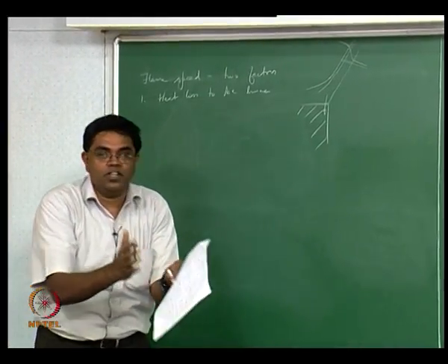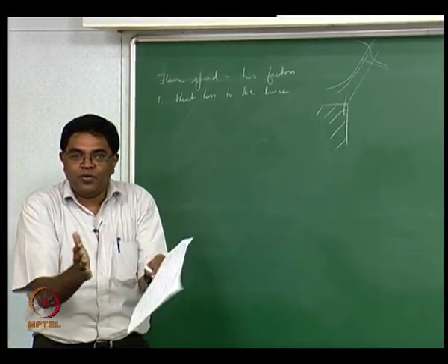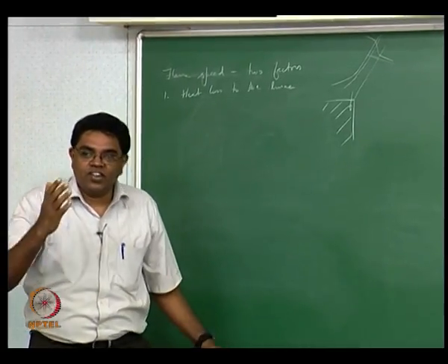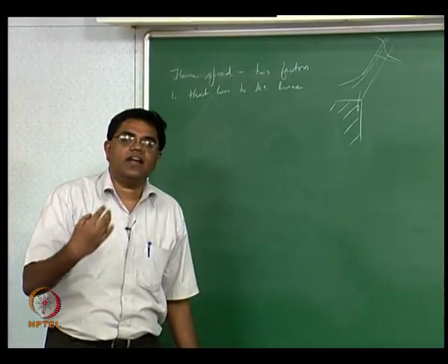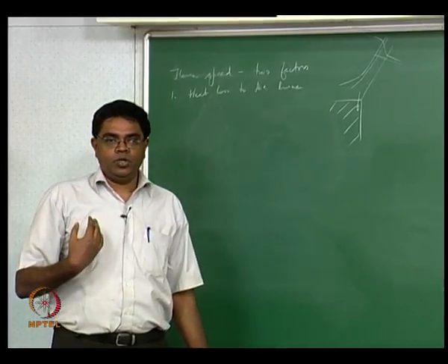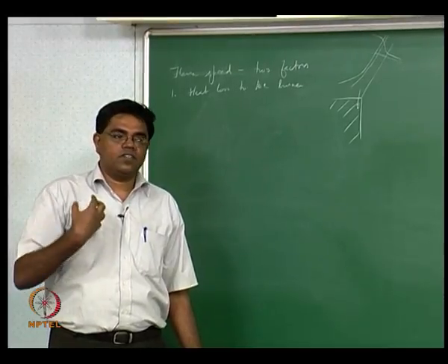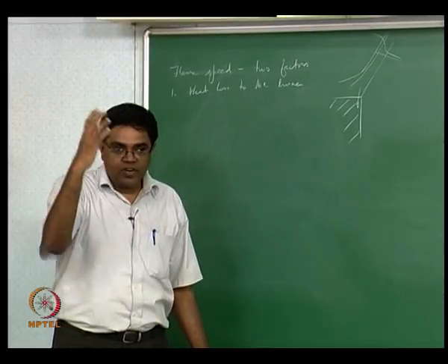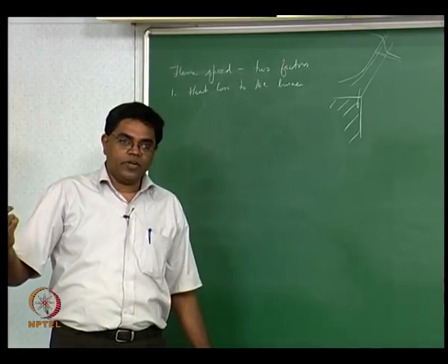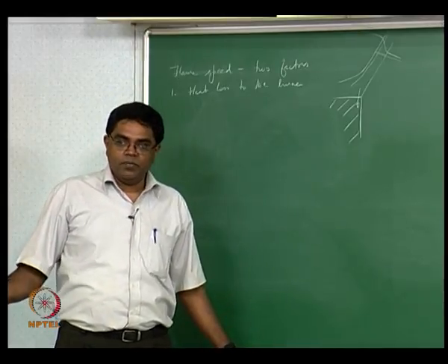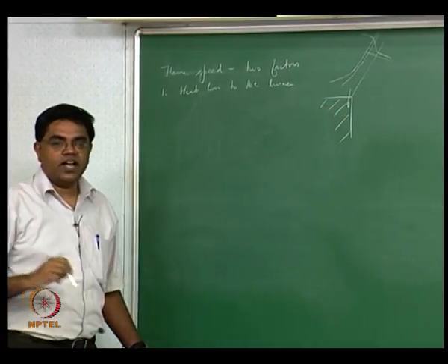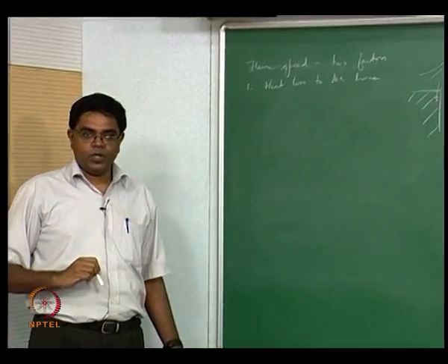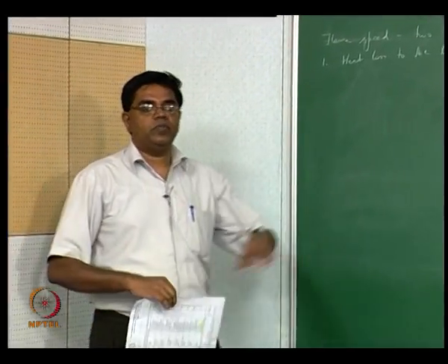The money is kept within the family, right? It's not going away. The reactants are the ones getting the heat and reacting in the flame. So long as the reactants get all the heat and then react to release that heat, it's an adiabatic system. But the moment the reactants are not the only ones getting heated up, that's not an adiabatic system. So obviously the local flame speed should decrease.